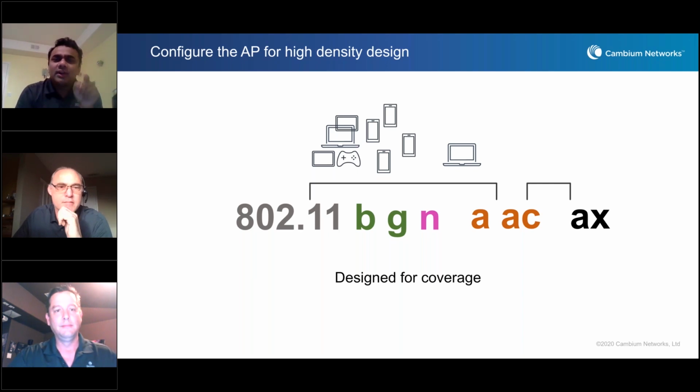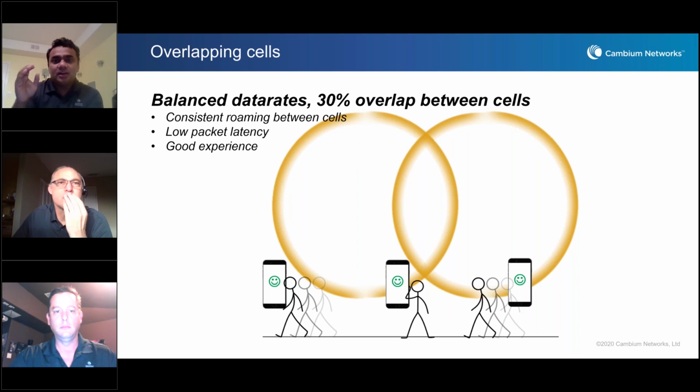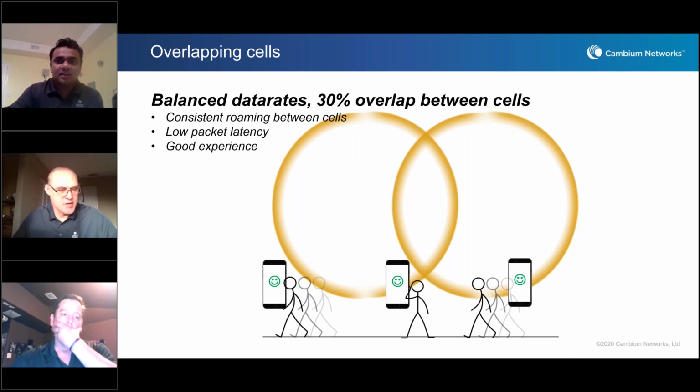Yeah, Darren, thank you. One point I wanted to add about the previous slide: every R distance, your power will be reduced. In a very practical sense, if R is a distance, and you get negative 50 dB RSSI, then if you go to 2R, you will usually see negative 6 dB down, so it will be negative 56. So every time you double the distance, you see a negative 6 dB RSSI signal loss.